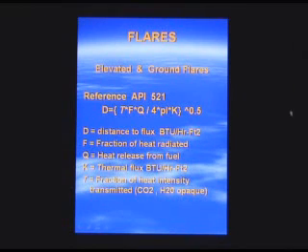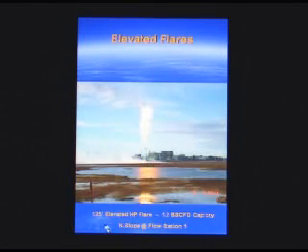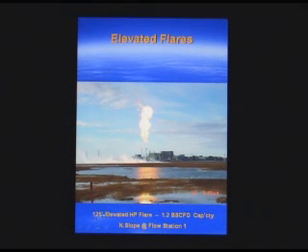So what that means is on some flares, as you go up in elevation, you can use the hypotenuse of a triangle to either each of the 10 points in the flame or to the central point of the flame, and that defines your distance from where you have to be to satisfy the maximum K value that you've specified. So let's go on here. This is an example of a 125-foot elevated flare at